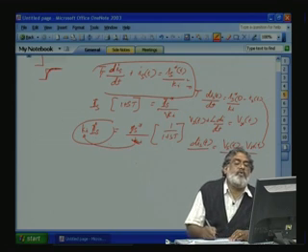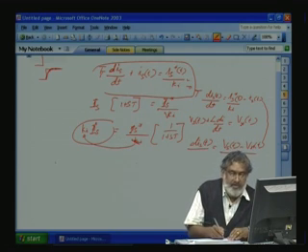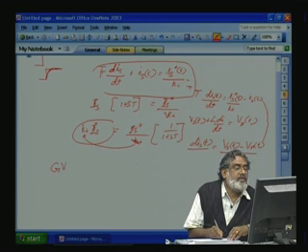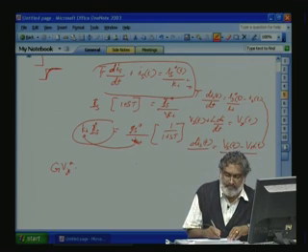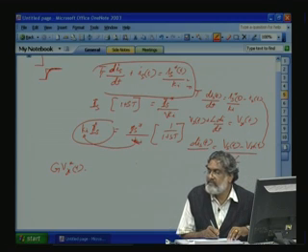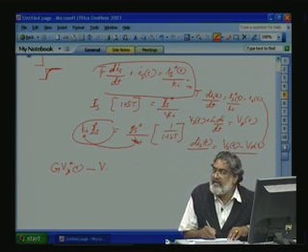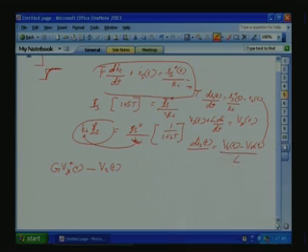So, VRT star is, according to a converter with a gain G, G into VRT star minus VST divided by L is equal to 1 by Ki into T into IS star, that is the reference, minus the feedback with a gain reduction from the converter loop. From this one we can find out what is VRT star.